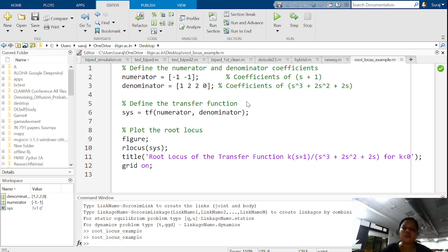So closed loop behavior would be of this sort. If it would always remain in the right half of the S plane, that means the system is not going to be stable. So the question that I showed you now was: the closed loop system of problem 1 is stable for, and you had options: for all k less than 0, for all k less than 1, for all k less than -2. There was a fourth option, no value for k less than 0.